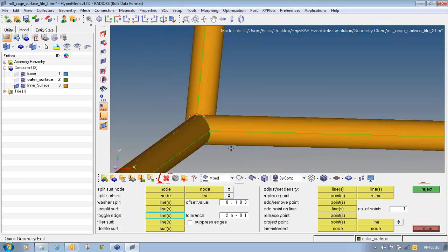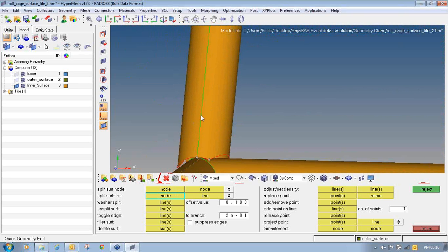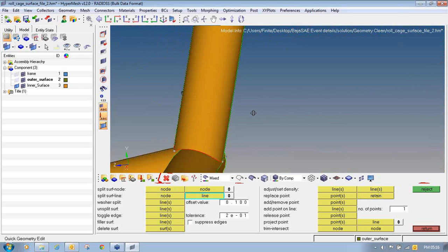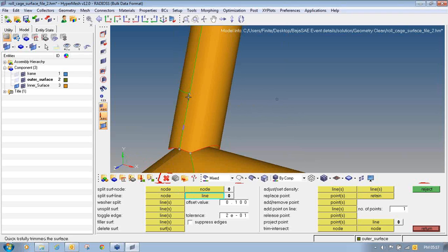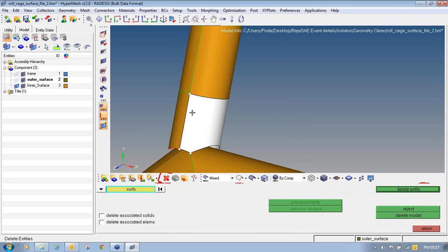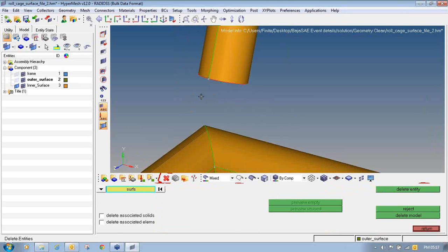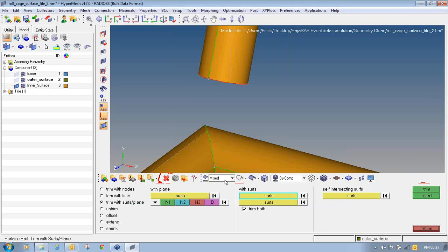Again I will follow the same process: first I will split up to a certain height. This geometry I will split, the pipe which I am going to connect. Then go to F2 and delete the surface. Then press Shift plus F9. Go to the extend panel.